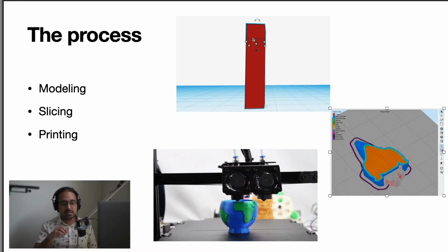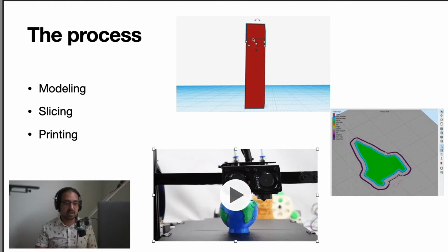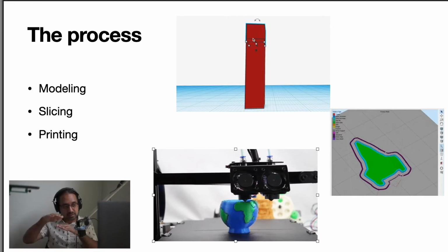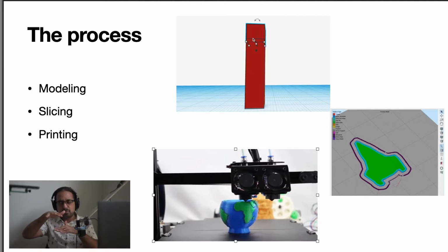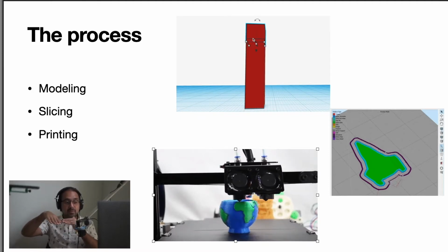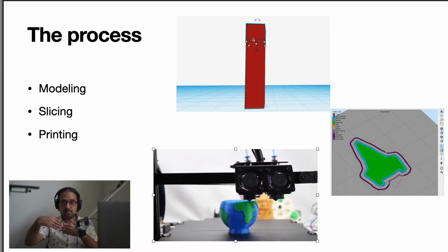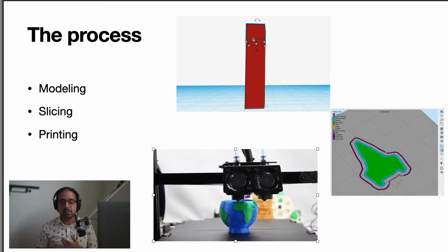Then those slices are turned into a series of control instructions for the printer. It will tell the print head how to move relative to the print base, and it will generate the model layer by layer by layer. So here's a fairly standard example, and at this point you would be fairly familiar with this. It'll turn that slicing directly into what's called G-code instructions. For most printers, it's called G-code, at least anyway. And those G-code instructions will tell the printer what to physically do. And you can get pretty fancy with the G-code.